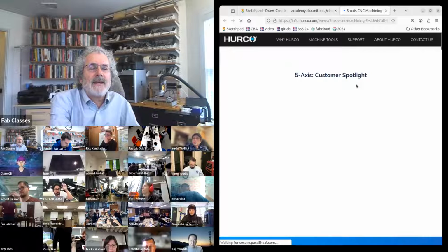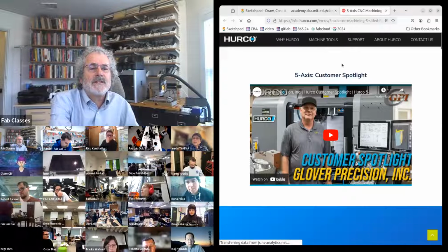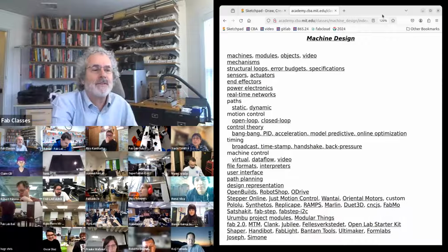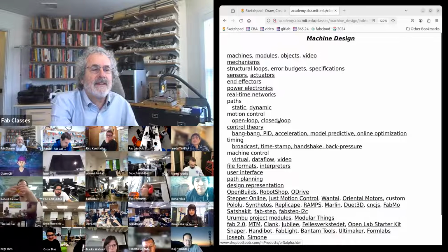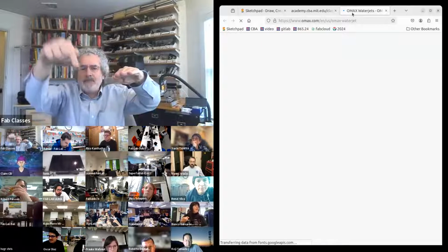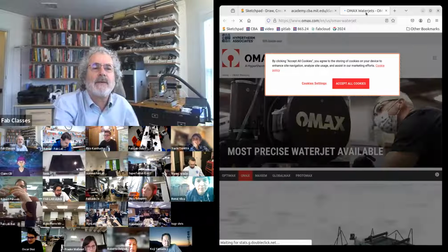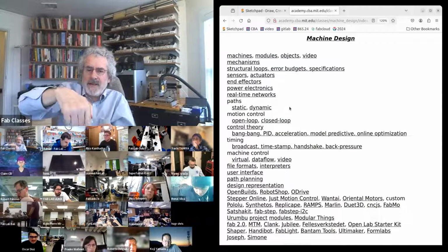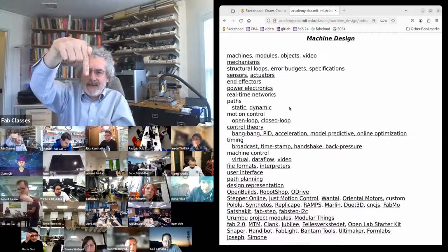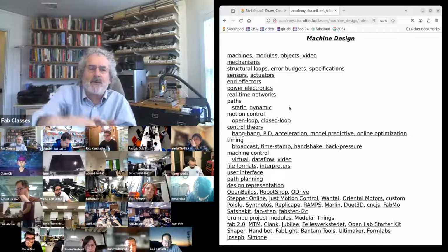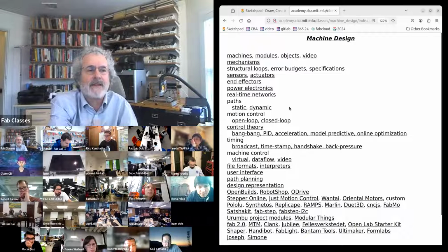This is a machine tool in my shop that is massive and stiff, and nothing ever moves. On the other hand, this is a water jet cutter, where when you're cutting, the whole jet of water is bending as you move. And so what that means is on the water jet cutter, to pick where the jet goes, you don't actually put the head where you want the jet to go, because the jet's moving. You need to actually account for it. So that's a dynamic path rather than a static path.